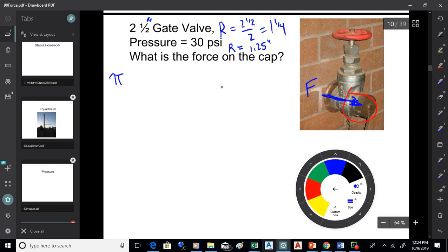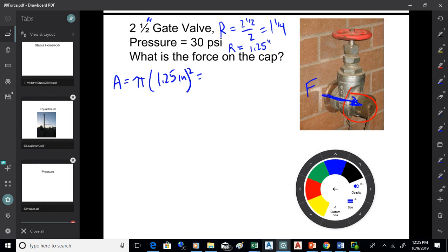So if you want that area, then you're going to factor that up. Okay, so the area will be pi times that 1.25 inches, and you square that. And is that the 4 point whatever? 4.9, yeah. 4.9? Okay, thanks. So that's 4 point. Check my logic. Yeah, I think we're good. Okay, and that's square inches, right?